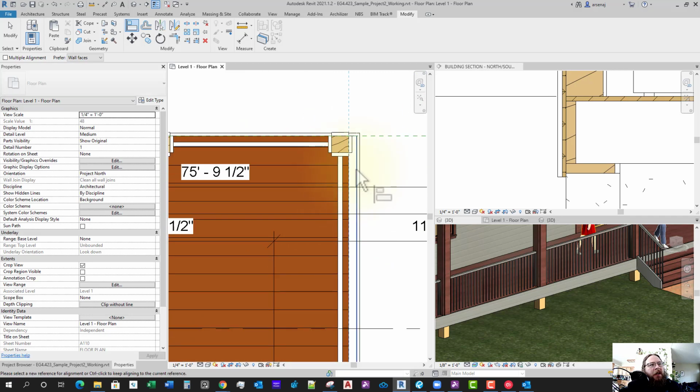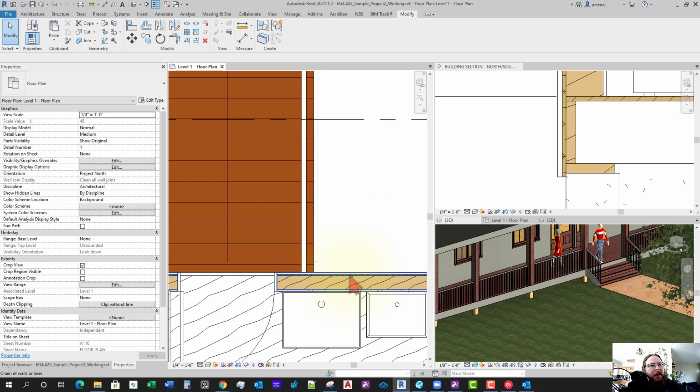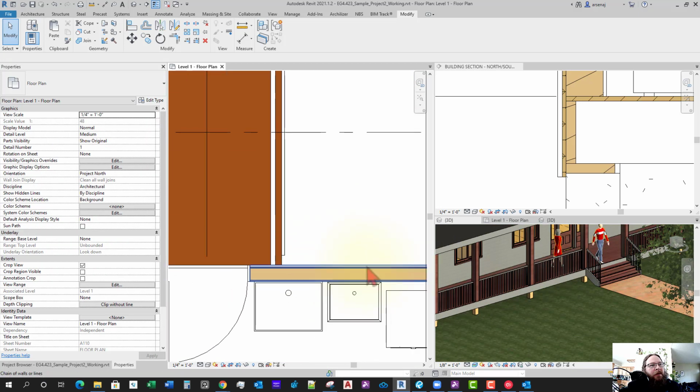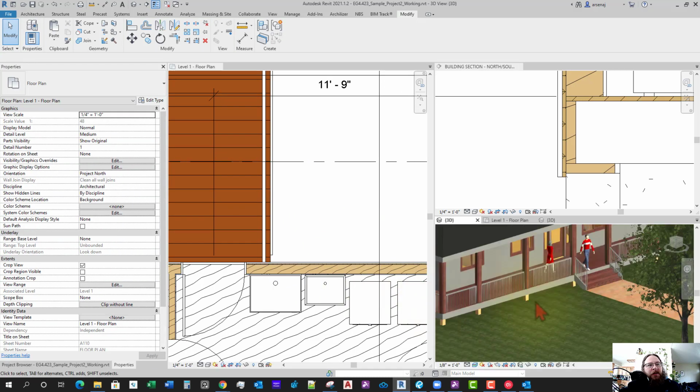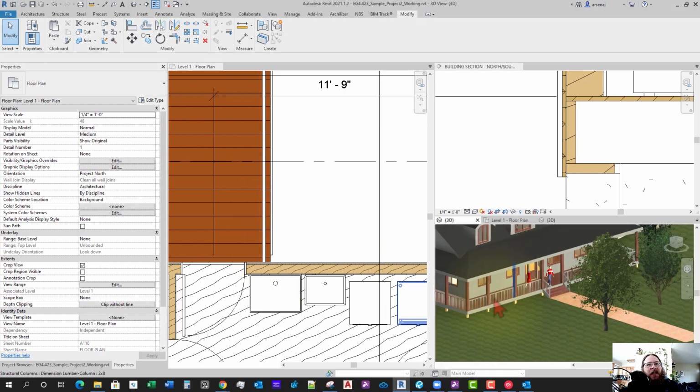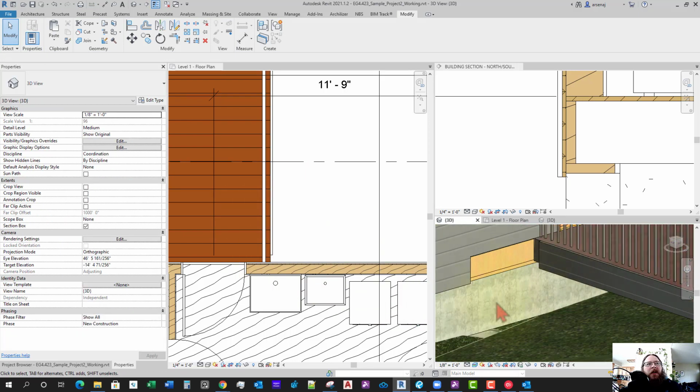And the last side here. And then what I'll do here for the last little bit, because I can't see it because it's underneath this wall, so I can kind of hit tab to try to grab it, but instead of trying to guess at it, I'm going to pan around to my 3D view, and I'm going to trim corner here. So I'm going to come up here, trim extend corner.